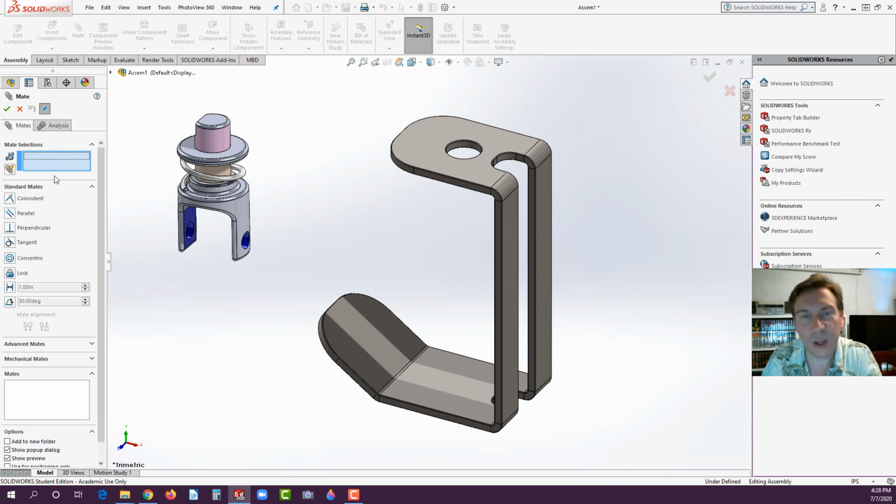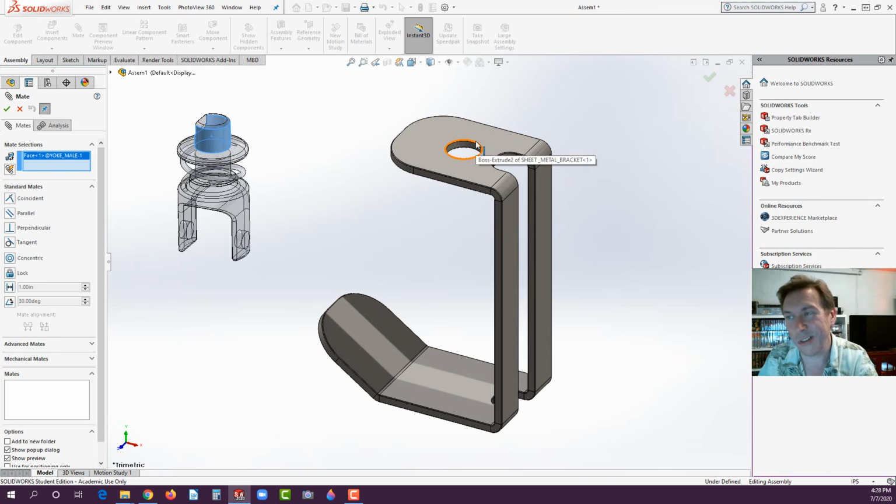The very first thing we're going to do, we're going to let it pick the best choice for what we select. So see this pink surface right here on the yoke male? That belongs inside this hole here. So go ahead and select this surface. Now before you click on that surface, be aware, depending upon the location of your model, yours might turn out a little different initially than mine, but don't worry. Okay, so just give it a moment. Don't hit undo just yet.